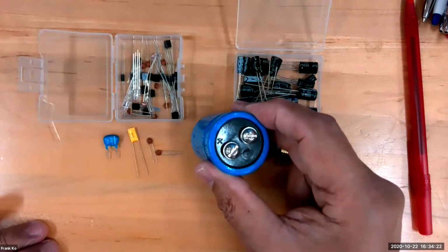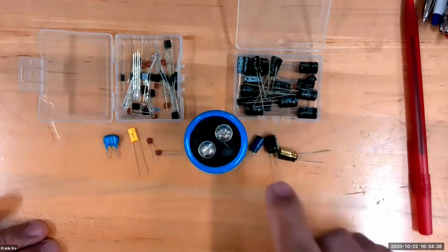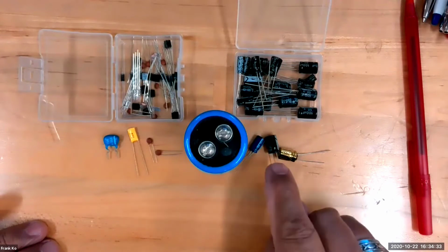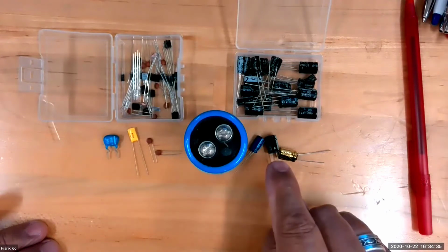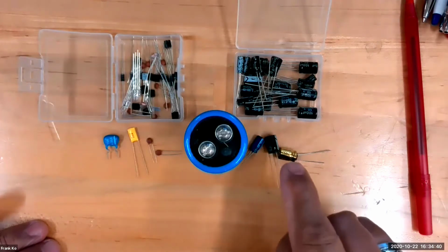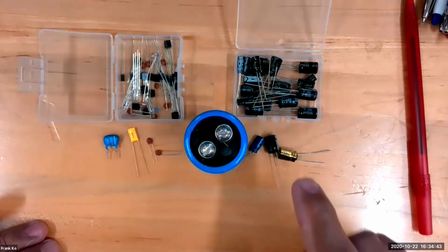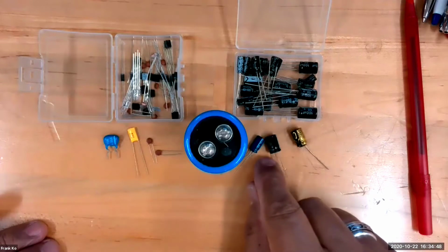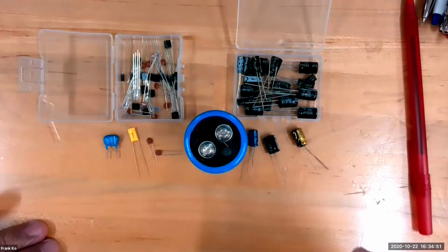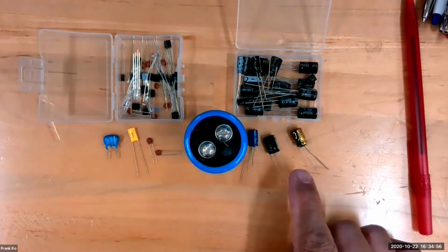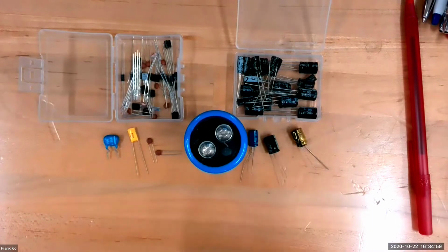We have to maintain proper polarity. Now, I will say this about the polarized caps. If you hook these guys backwards and you apply enough voltage, they will explode. What will happen? They will explode. And that has happened in lab. As often as I have told students over and over again, be mindful of polarities, don't hook these up backwards. A momentary backward won't hurt anything. But if you have enough voltage on this, and it is backwards, these things will explode.